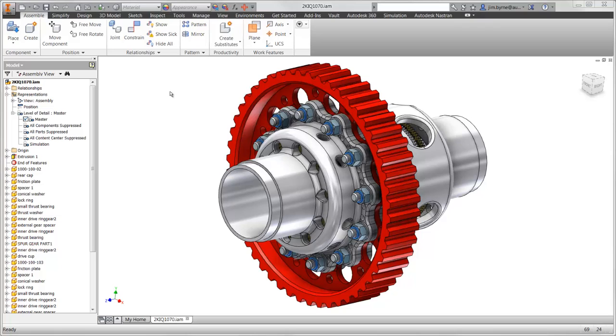Taking a close look at the design, we have several bolts, nuts, and washers being used to fasten the components in the assembly. There are a couple approaches that can be taken to set this analysis up. First, we can analyze the bolts as they are and gain some knowledge of the stresses on each of them. The second approach is the use of connectors.